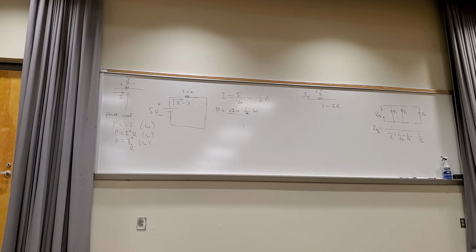Think about it. Let's make it nice and simple. Hairdryer's using 1,000 watts. Wall voltage is not 120, say it's just 100 volts. It's a DC equivalent, it's called RMS, root mean squared value. It's really 117. Call it 100, right? So how much current would be there? About 10 amps, right? Now 10 amps, I'm trying to give you a feel for this stuff, because you're going to be engineers in the field. 10 amps for a hairdryer, yeah.